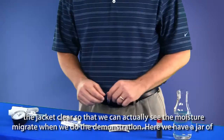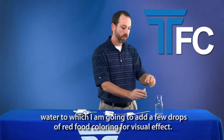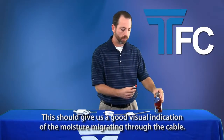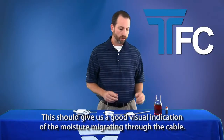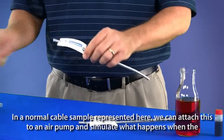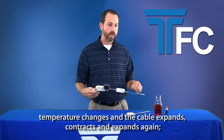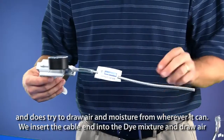And then here we just simply have a jar of water to which I am going to add a few drops of red dye food coloring just for visual effect. We're just going to give that a little swirl, get it all mixed in. And this should really give us a very good visual indication of the moisture actually migrating through the cable. In a normal cable sample, which is represented here, we can attach this to an air pump, and what we're going to do is simulate what happens when the temperature changes and the cable expands and contracts and then expands again and does try to draw air and moisture from wherever it can.